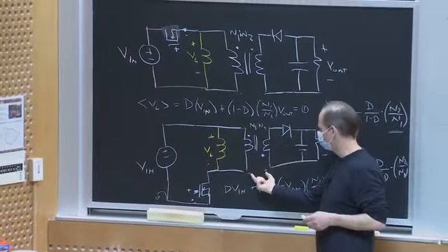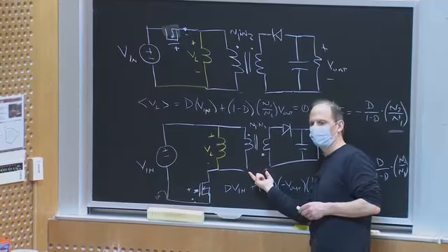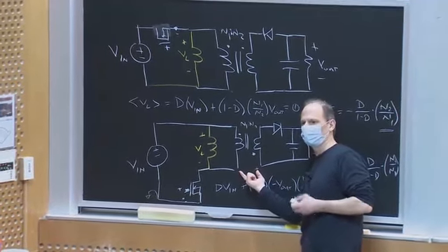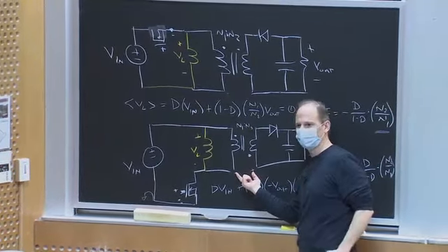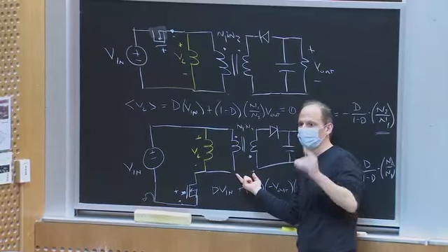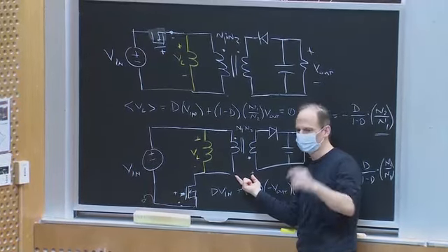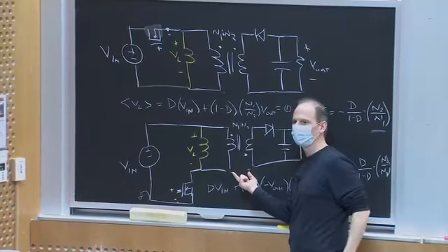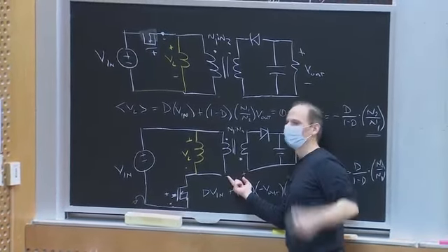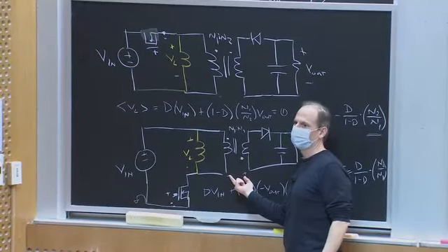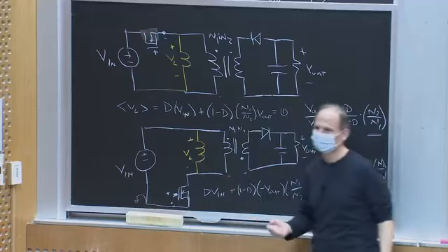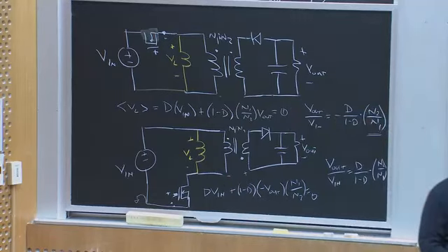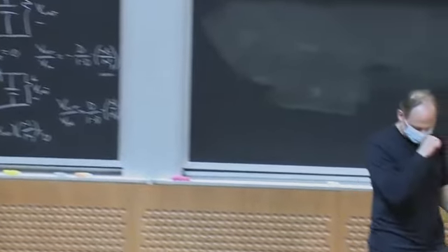this isn't perfect. The ability of the transformer to take voltage this way depends upon how much insulation you have between the primary and secondary, and that's what's regulated. So it's a few thousand volts typically for a laptop adapter. And like I said, even if you have a fault on one of those layers of insulation, the other one should be big enough to block a few thousand volts. Does that answer the question? Okay, so